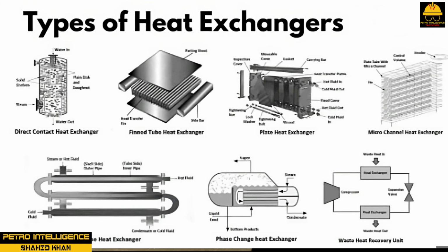In pipe coil exchangers, pipe coils are submerged in water or sprayed with water to transfer heat. This type of operation has a low heat transfer coefficient and requires a lot of space. It is best suited for condensing vapors with low heat loads.